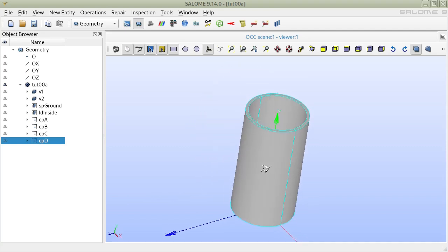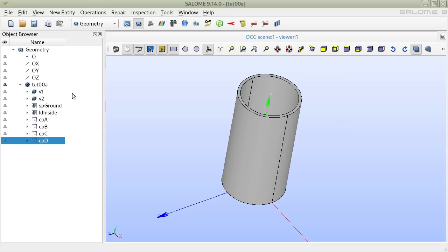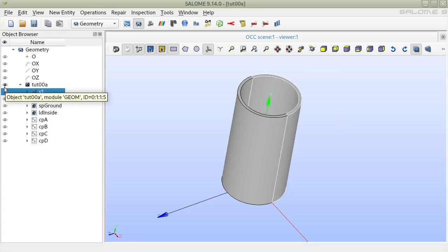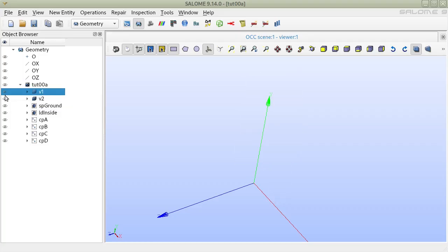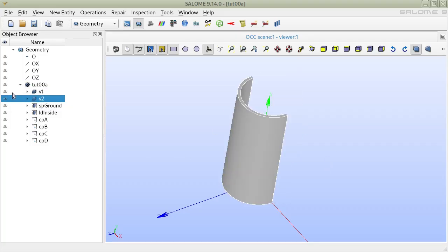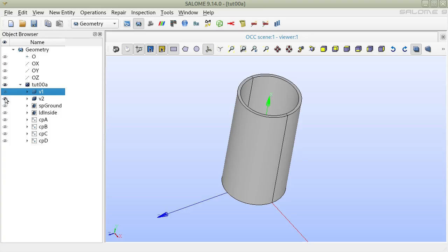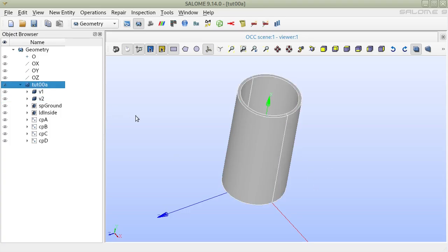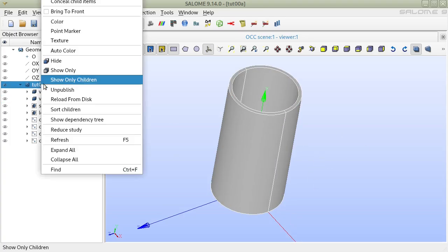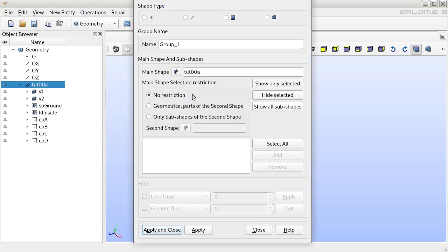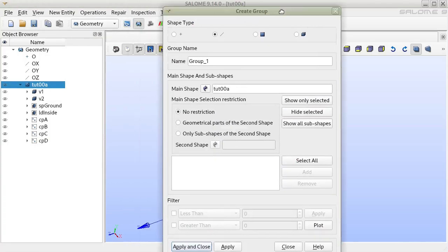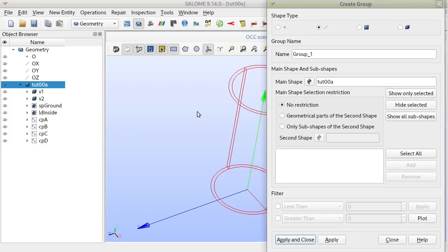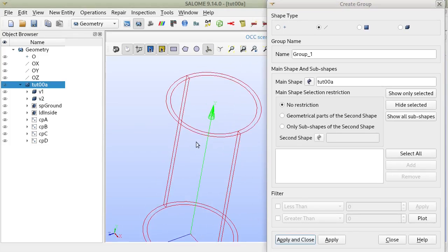So now we need to define the lines of the surface we want to extrude, the top surface, the top base of the cylinder. The 4 lines on the top base. We will use these lines to subdivide the surface and then extrude it.